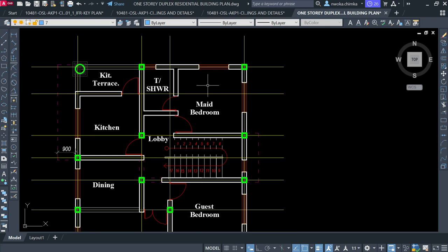Two things make sound pass through the slab. One is when the panel area is not met based on the BS codes. Two is if you design your slab bar spacing to, let me say, 200 or 150 or 175, and then during construction they use a very large spacing of, let me say, 300 or 350. Those kinds of things will cause that kind of issue.